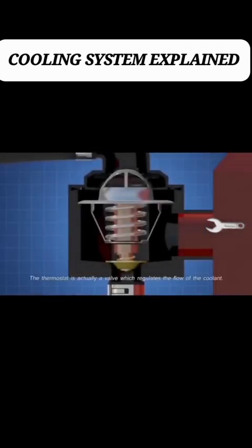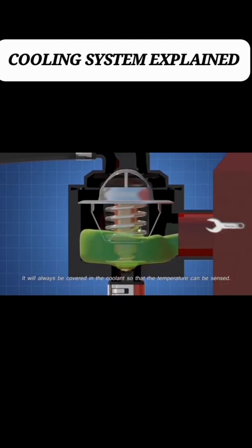So, finally, let's get into the working, starting with the thermostat. The thermostat is actually a valve, which regulates the flow of the coolant. It will always be covered in coolant, so that the temperature can be sensed. Let's start the operation from a cold engine.